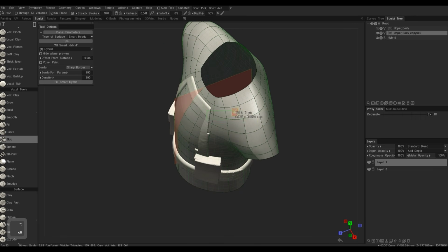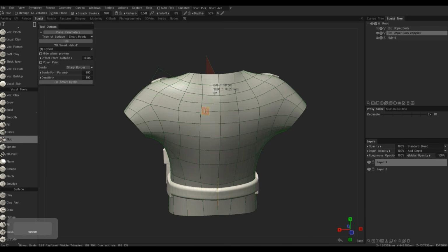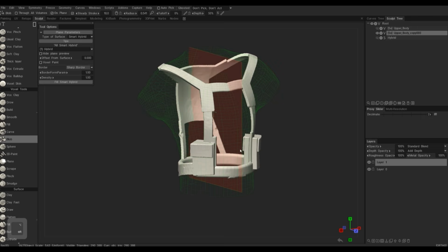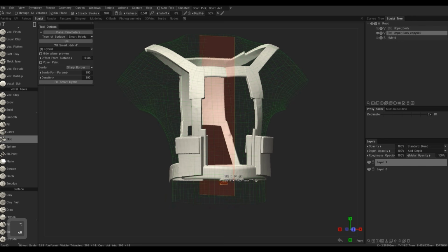And again, you do want to face your camera and projection, rectangular in this case, in the same direction. You want to make sure your camera is looking straight down, otherwise it creates a bit of distortion. I can also hide the hybrid. I keep it there visible just so I have some kind of visual surface to deal with. When it gets this see-through mode, it gets a little bit annoying.